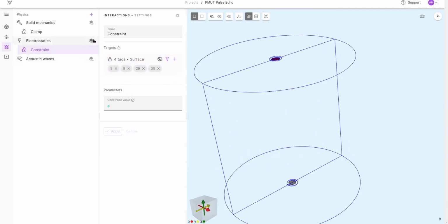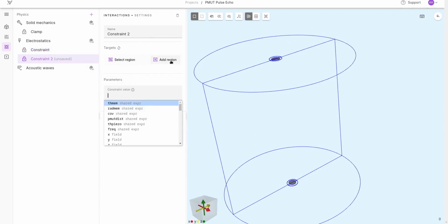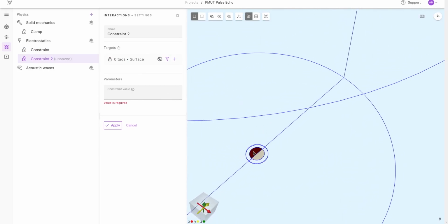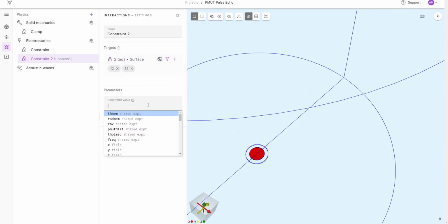Next step, we define a signal. So here you could drive with charge drive or voltage drive. For the driving, I will just drive with a voltage imposed. So this will be on the top side of the piezoelectric layer here. And I could define whatever here, wavelet or a sine wave or anything myself. But what I will do is just put a dummy 1 for now,